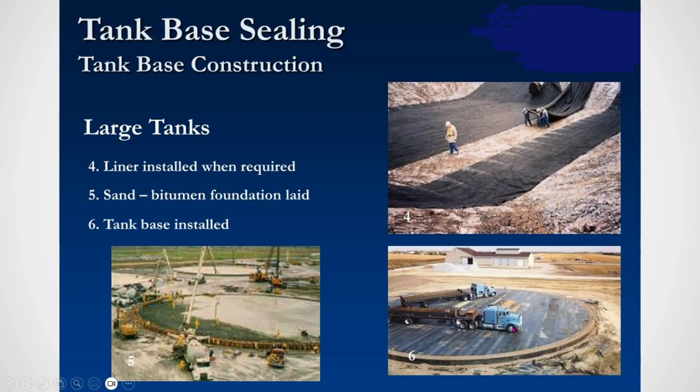And then the bottom plate, you see, that is the bottom plate. So first the foundation, then above the foundation there will be a liner, so that if any water is there, it will not go up. Then there will be sand, and above this sand the bottom plate will be placed. You have to take care so that moisture will not come in contact with the bottom plate.